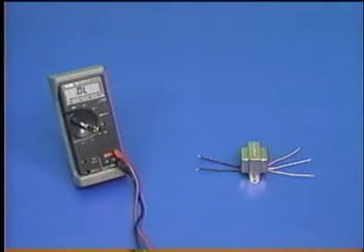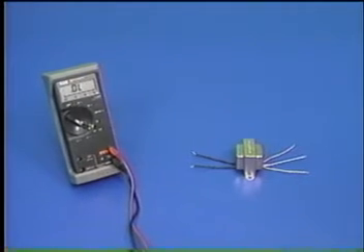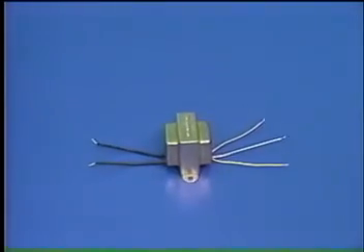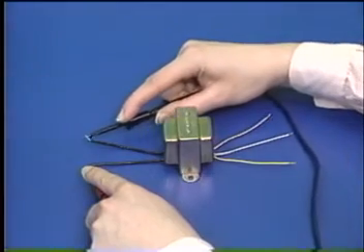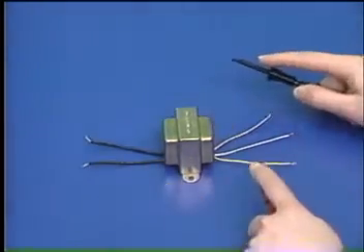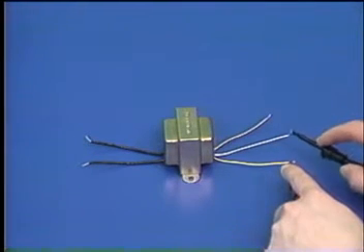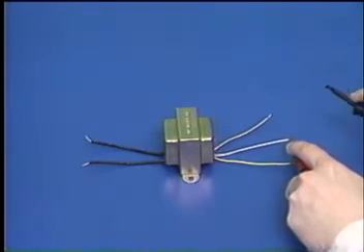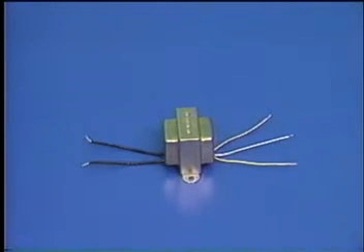Let's use the digital multimeter to check the transformer for broken or shorted out wires in the primary and secondary windings. First, attach the spring-loaded clips and check the 2 ends of the primary winding. You should hear the tone that indicates continuity. Next, check for continuity between one end of the secondary winding and the center tap. Then, check from the center tap to the other end. Again, you should hear the continuity tone.